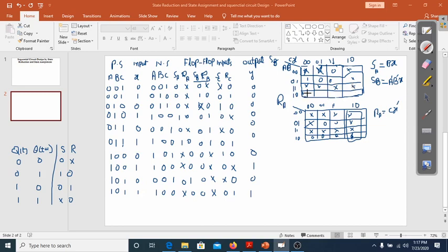So here SC is 1, then 0, for this combination 0, this is don't care. So here you can see I can simplify the first column with the last column. When I simplify this, this whole column will cancel out. The C complement will cancel with C, so I will get SC is equal to X complement.